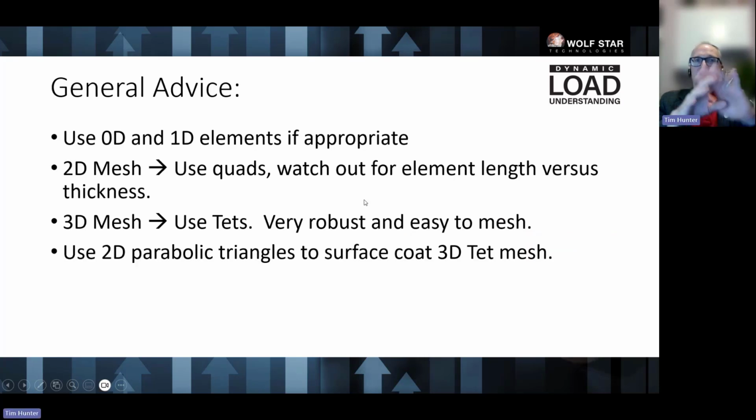Okay. General advice here, okay? General advice here is use 0 and 1D elements when possible. 2D mesh, use quads. 3D mesh, use tets. And 2D parabolic triangles to surface code a 3D mesh, okay? So that kind of wraps it up for my side of it here.